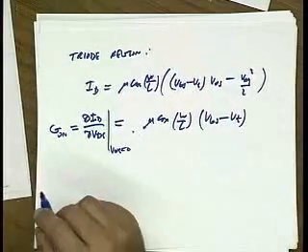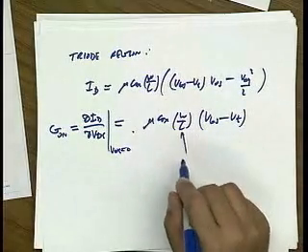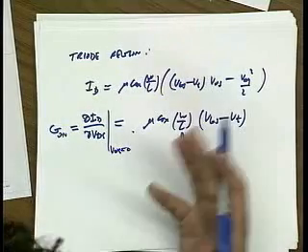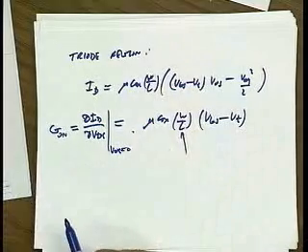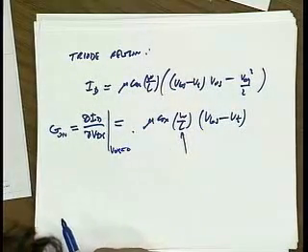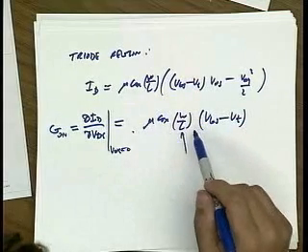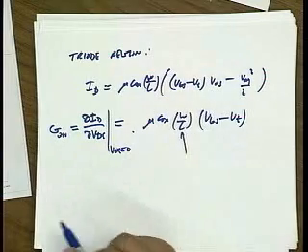Okay, so with process scaling, by making L smaller and smaller, I'm able to make this switch more and more conductive. And there was historically a turning point somewhere around, let's say, 0.35 micron, where the switch on resistance with a reasonable switch size, and I'll talk about what I mean by reasonable switch size, was low enough that it wouldn't de-Q your tank.